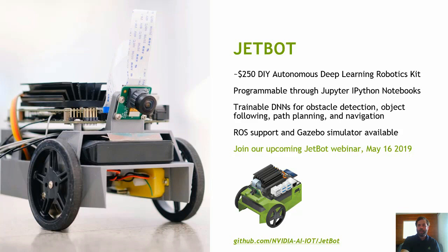Out of the box, it can do obstacle detection, object following, and path following using TensorFlow and TensorRT from a low-cost monocular camera feed. You can even collect new data from your environment right in the IPython notebooks and retrain the networks on board the Nano, so it's very easy to use and create new autonomous modes for. We've also released ROS nodes supporting the JetBot hardware, along with a Gazebo simulator model for it, so if you're a ROS user, you can bring ROS components to JetBot too.